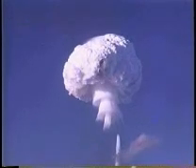Here we've generated a toroidal vortex ring by injecting milk into a small aquarium at a Reynolds number less than 1,000. The infamous mushroom cloud from an atomic explosion is a similar physical phenomenon, only here the Reynolds number is at least several billion. Fluid dynamic similarity between the two is obvious by visual inspection.